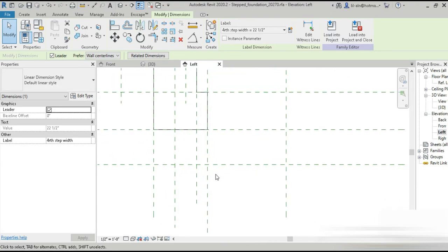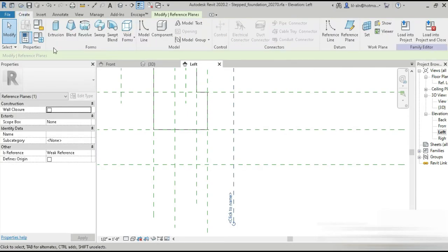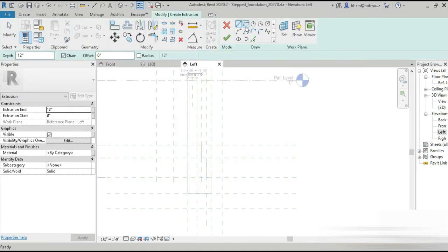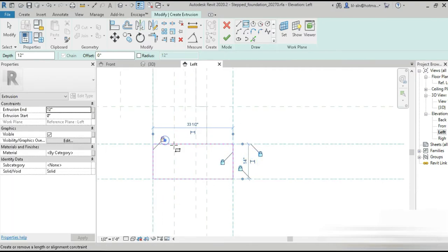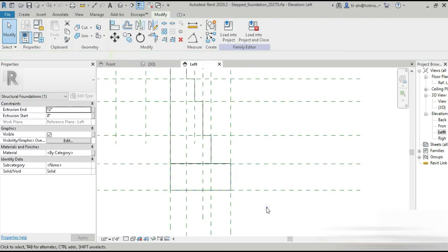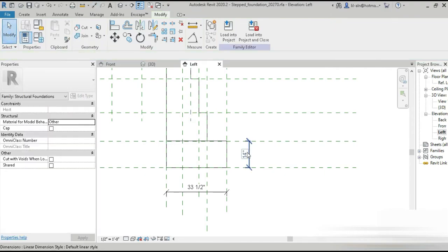So now the PCC, time for the PCC. This is the reference plane that I made for the PCC. It's exactly the same thing as we did previously, but it's only editing the shape a little bit, bringing all those bricks to the other side. So extrusions, rectangle, and right here to right here. We lock all our axes, and okay, all our axes are locked. So now it's the same as before. Dimension from this point to this point right here, and the dimension from this point to this point right here.